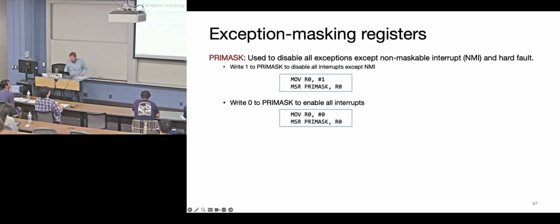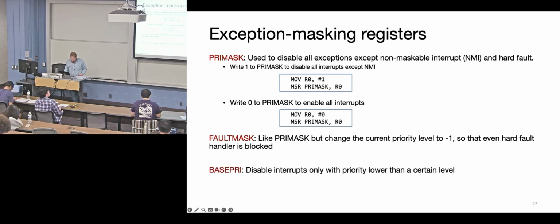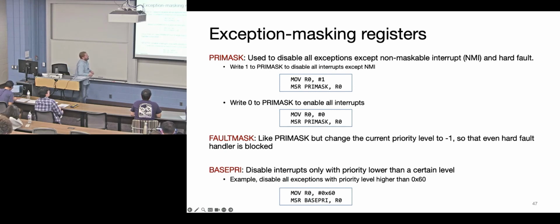You can disable some of the non-maskable interrupts, like hard faults. And with the fault mask, you can actually disable the negative level 1 priorities. This was the fault priorities. So your code is so important that you don't even want a certain number of faults to be triggered, leaving only the reset handler, and I forget the other handler. The number 3, the highest, and the second highest, the -1 and -2. It's just so you have options. Okay.